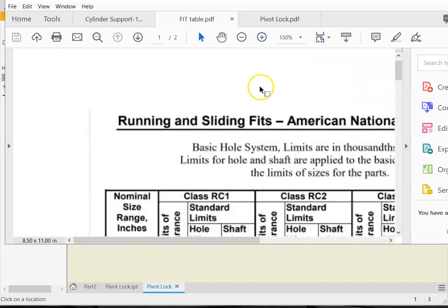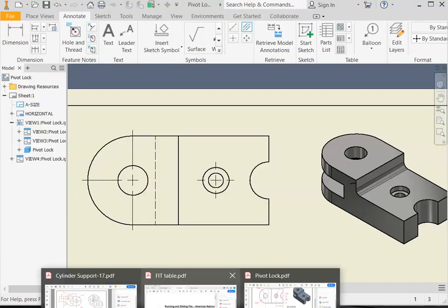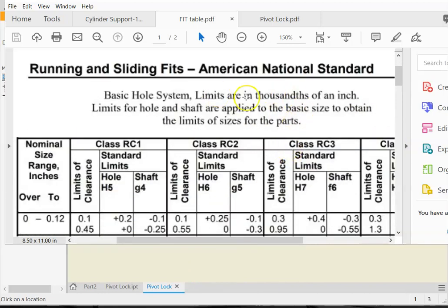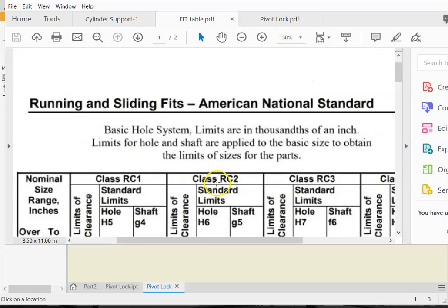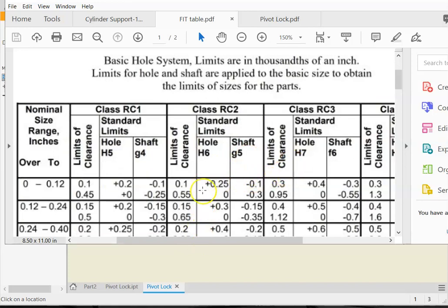I tell you on this top portion here that all the numbers are in thousandths of an inch. So that's what you read. You need to divide by thousands. The reason for that, of course, is that there would be so many decimal points and the column would be too wide to show all these. So what they have done, they have multiplied every number by 1,000, and then we, as a user, will use the fraction 1 over 1,000. So multiply by 1 over 1,000 or divide by 1,000.